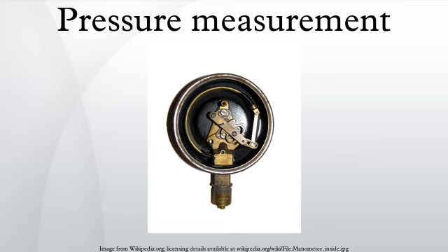The positioning of the indicator card behind the pointer, the initial pointer shaft position, the linkage length and initial position, all provide means to calibrate the pointer to indicate the desired range of pressure for variations in the behavior of the Bourdon tube itself. Differential pressure can be measured by gauges containing two different Bourdon tubes, with connecting linkages. Bourdon tubes measure gauge pressure, relative to ambient atmospheric pressure, as opposed to absolute pressure. Vacuum is sensed as a reverse motion. Some aneroid barometers use Bourdon tubes closed at both ends.